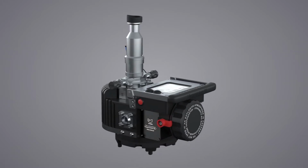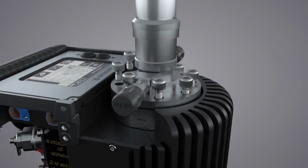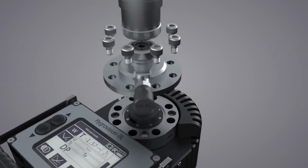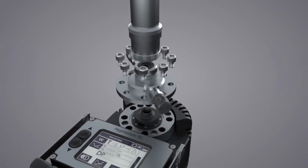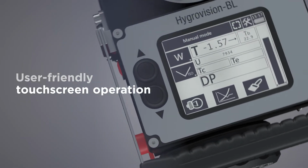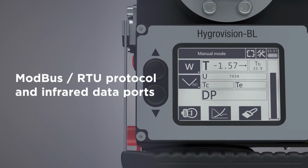This makes the Hygrovision-BL essential equipment for those sections of the oil and gas infrastructure where continuous measurement of gas humidity is required. In order to have a clear view of the condensation mirror, the microscope is mounted directly onto the high-pressure chamber. Measurement processes, including changes in mirror temperature, are controlled by an electronic unit. This unit is operated by means of buttons and a touchpad.